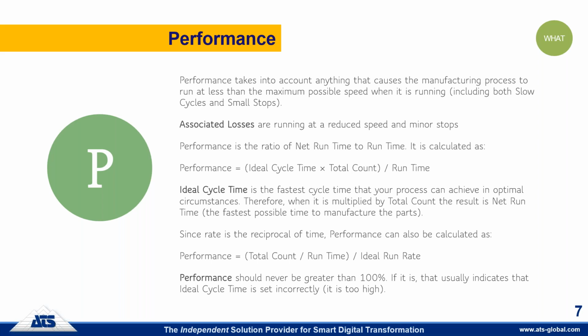If you have a lot of part variation, then it's very important that this cycle time is tied to the parts that are running through that piece of equipment at that particular time, to get meaningful value out of this. Don't be tempted to use reduced cycle times. A lot of people are tempted to use budget cycle times or standard speeds for OEE, or maybe they'll use the cycle time that they happen to be achieving at the moment. If that's slower than the optimum speed that the piece of equipment or the process or area or person can accomplish, then you're just robbing yourself. Your OEE will look good, but it won't be true OEE, and you'll be fooling yourself and hiding potential production gains that could be made.